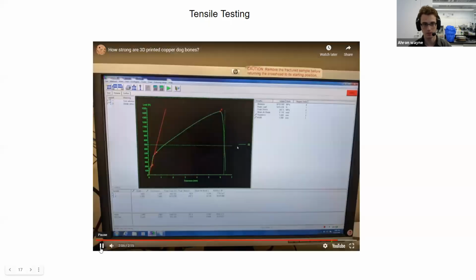Before it finally breaks. Before, at the lower temperature, we had a peak force of 600 newtons. And then at the higher temperature, we had a peak force of closer to 1,500, so more than twice as much. And then our ductility was also about twice as high. So we were getting 50 to 60% extension, which is pretty close to the ideal for just wrought copper.